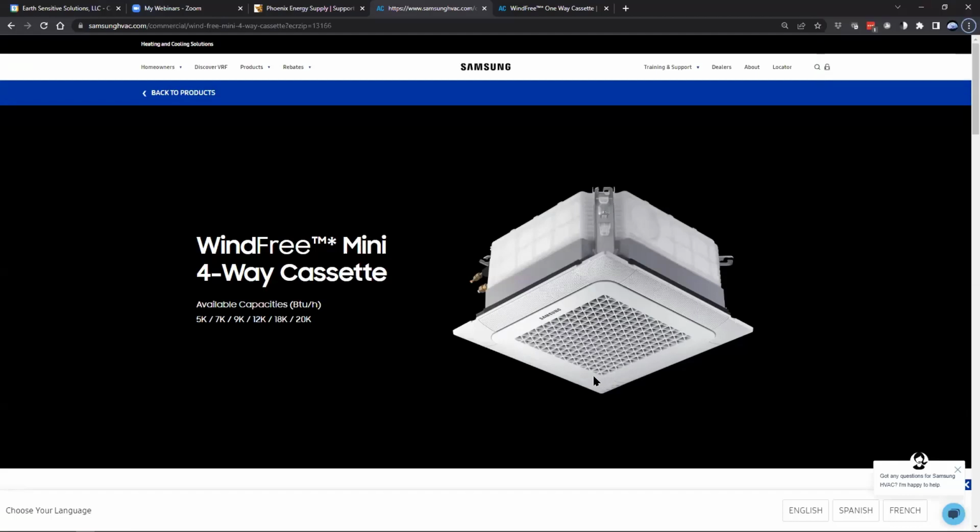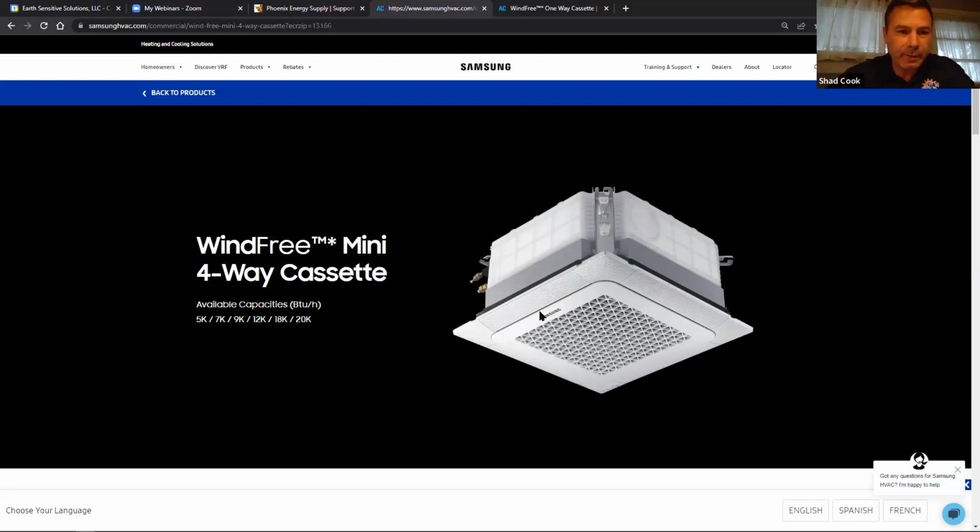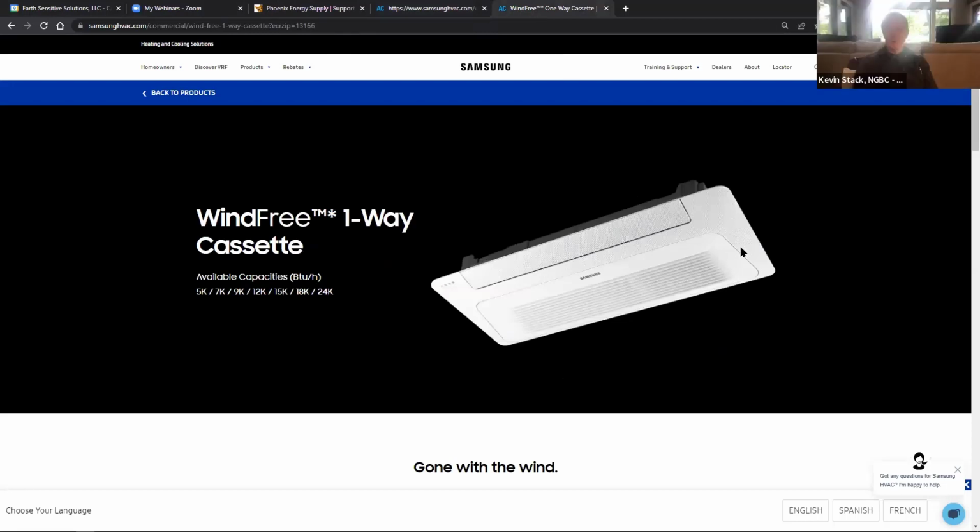Yeah, obviously this would be much easier to hide, especially if we're talking about a ceiling cassette. Then you could just build some sort of lattice around it to blend it in. Sure. Maybe hide a light behind it, make it a decorative fixture. Yeah, Matt, what everybody's got to consider here is the space we have in framing without having to box out areas. Probably the one-way cassette would be the only thing, even if that is less than 14 inches in width, John. I know most of them are intended to fit within a natural joist space, but they don't. I learned that the hard way. Yeah, so when we put the second floor deck on, we would have to space the joists appropriately if we're going to be doing this.